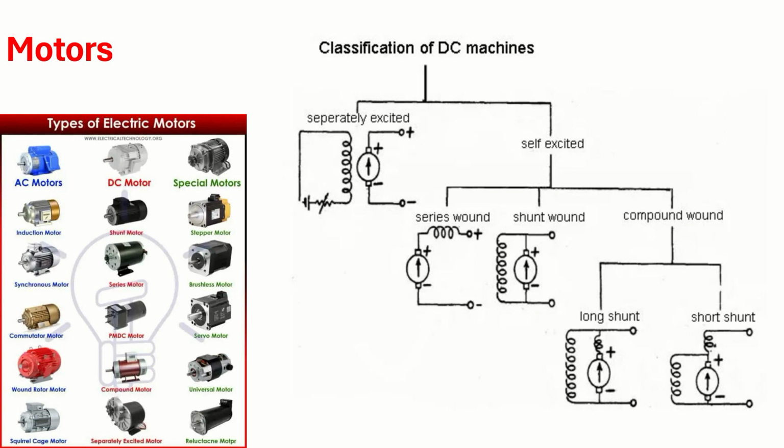The reason is that the technology is now so advanced, your CPUs are so advanced, and the drivers, that's MOSFETs and IGBTs, are so advanced that converting the energy from AC to DC, DC to AC, and generating the desired signals is not a big problem. Because of this advancement in semiconductor technologies, people prefer AC motors. So it's no more a challenge in controlling the AC motors. Because of the maintenance issues, they have now discontinued DC motors.